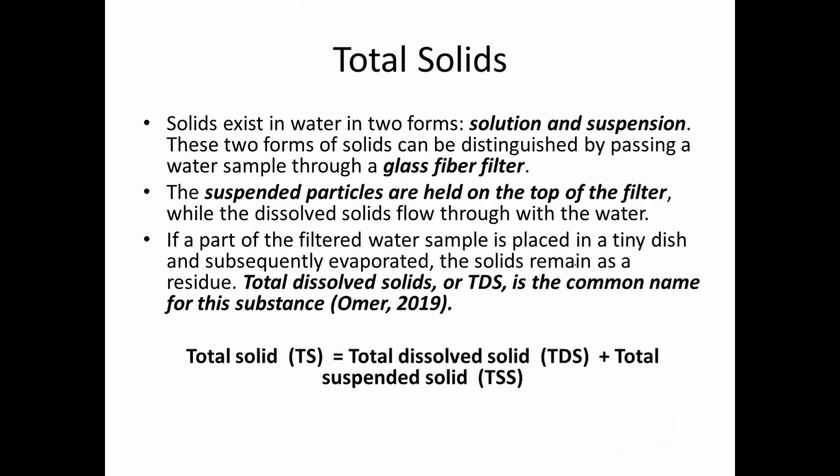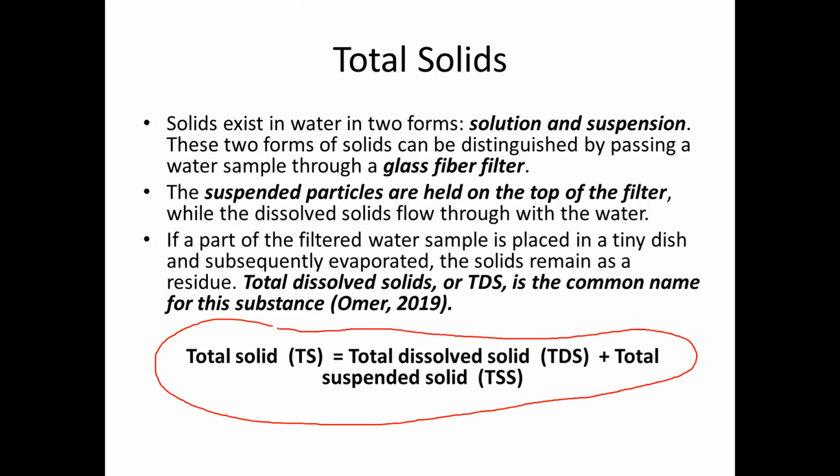Total solids. When we talk about total solids, it could be dissolved solids, which we cannot see with the naked eye, and those visible to the naked eye are total suspended solids. The suspended particles are held on top of the filter while the dissolved solids flow through with the water. So when there are suspended solids in the system and you filter it, you get clear water.